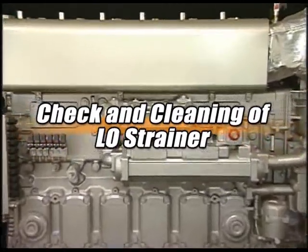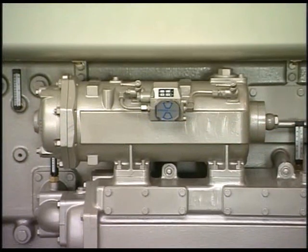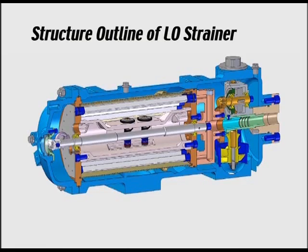The lube oil strainer fitted on this engine is the automatic backwashing filter. I will explain the mechanism by using the sectional view. Lube oil is filtered by running from inside to outside of the strainer element. The cleaning nozzle rotates during the operation by the turbine that is driven by the lube oil pressure. At the tip of the nozzle, the flow of the lube oil is reversed, dirt is discharged, and filtration and cleaning are constantly repeated.